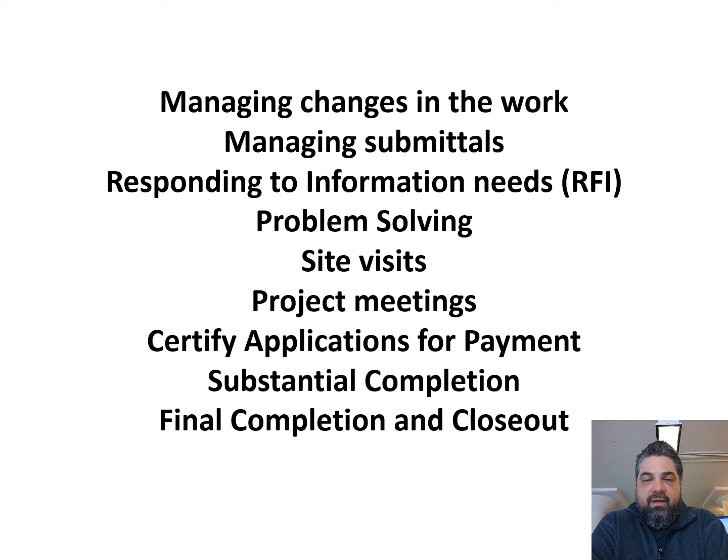Sometimes you'll be having meetings that aren't necessarily on site, but they will be what are called OAC calls or meetings, owner, architect, contractor meetings during construction, which could occur weekly or bi-weekly or monthly. You'll be asked to certify applications for payment. So applications for payment, or pay apps, are essentially a bill from the contractor to the owner.